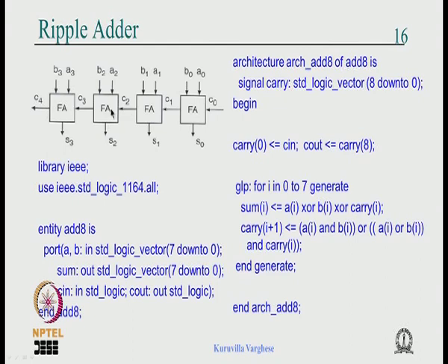Or when you come to the third stage, instead of just using B2 A2 S2 and an already formed C2, we will use B1 A1 B0 A0 Z0 C1 everything to generate it in one shot, not rippling through the stages.